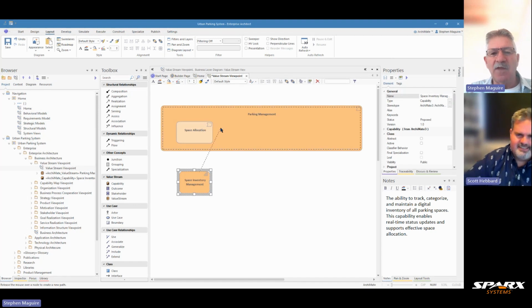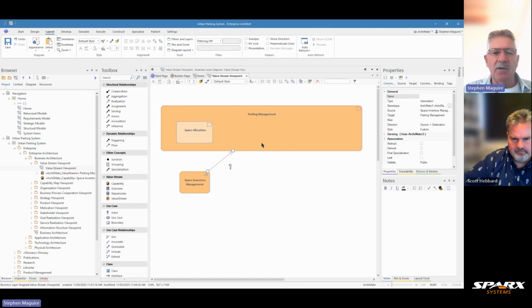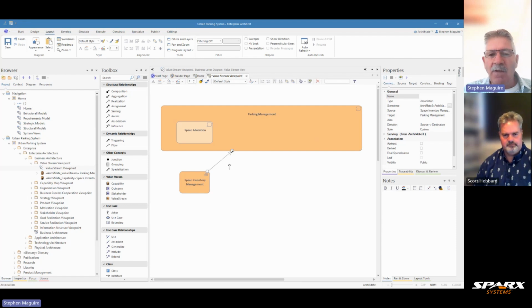You can see as I change that, I can see which one's selected now. So yeah, and let me say, Scott, if I put it here, which wouldn't be wrong, there's nothing semantically wrong with that, except it's not what I want to do. I have the capacity, rather than deleting the connector and starting again, if I roll my mouse over the end of that until it turns from that crosshair into a little arrow, I can grab that connector, and I can now put it onto this element.